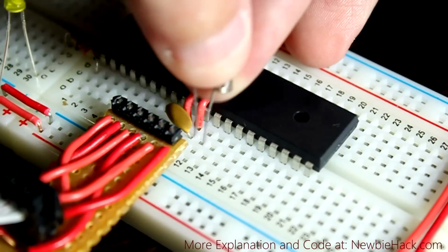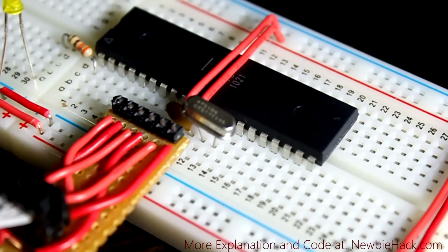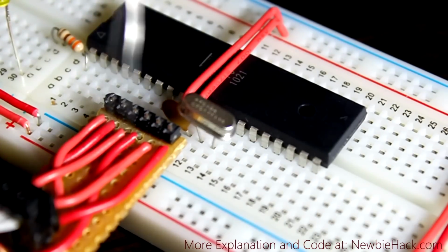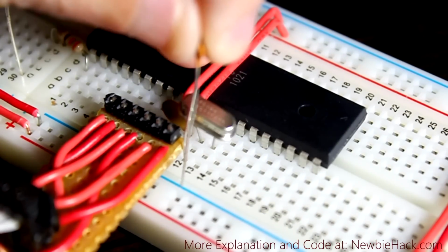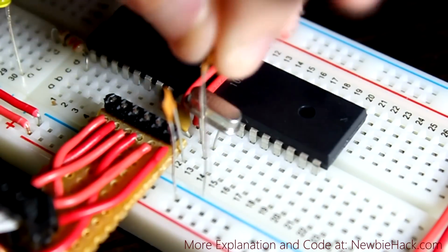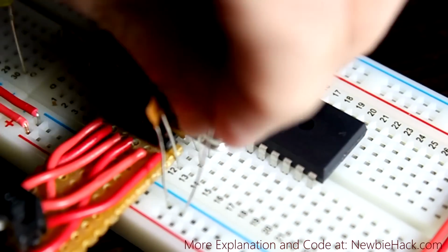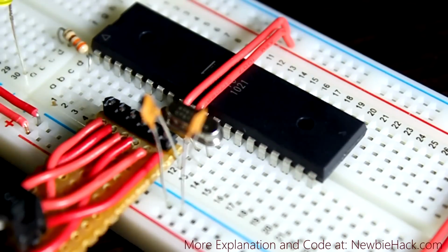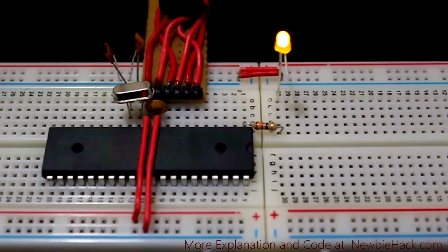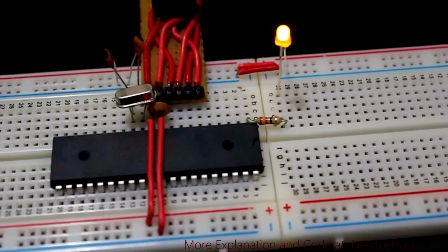So let's go ahead and add the crystal to 12 and 13. Let's add the capacitors to ground from 12 and then from 13. And now we can plug it in and see if it works. We should have a fast blinking LED. And sure enough, it worked. You can see that the blinking is very rapid now.